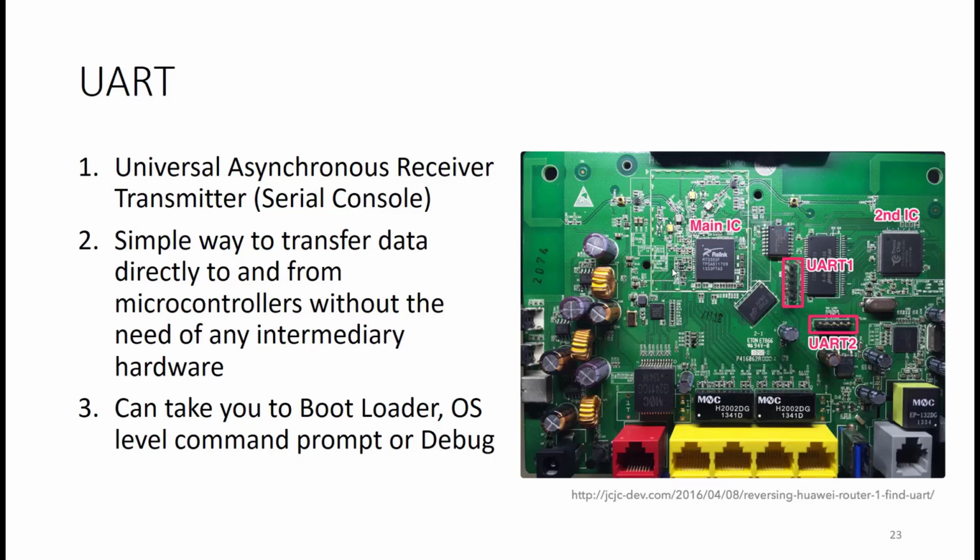And since it is a direct debug connection between two components, you can tap in between this connection and see and sniff the data which is going between this communication. Since UART is also being used for debugging purposes, you can actually dig into this interface and see what data is going. Also, you can run some system level privilege commands on the UART shell and get most of the data out of this UART.